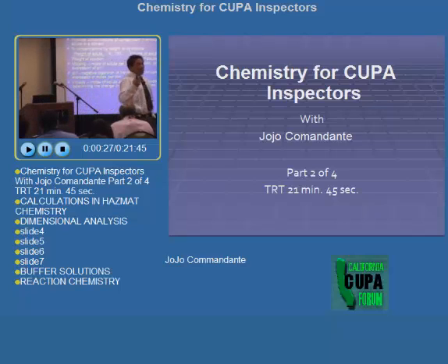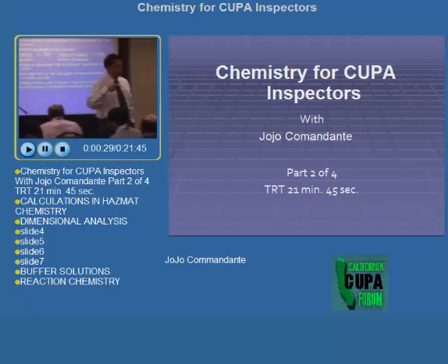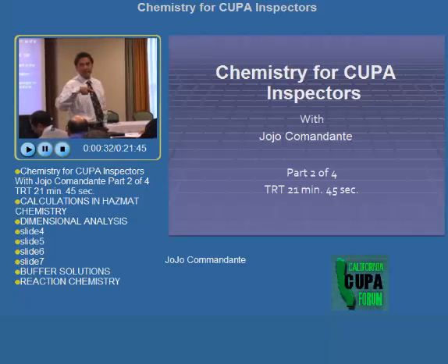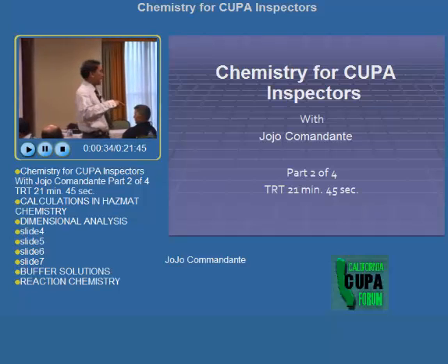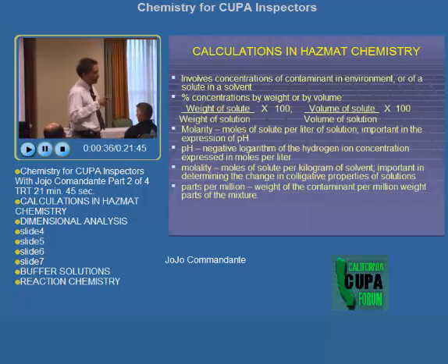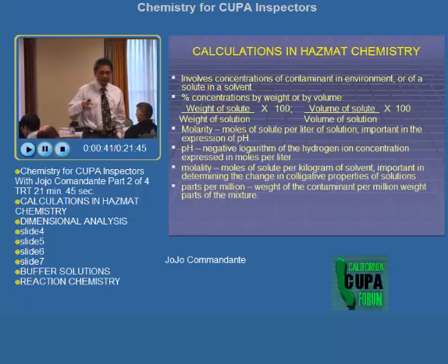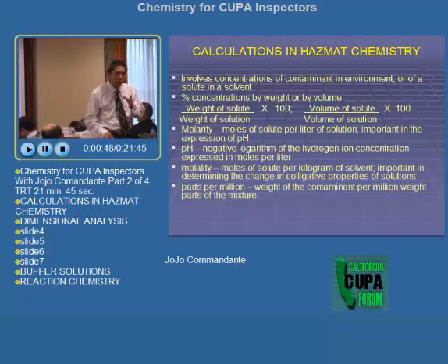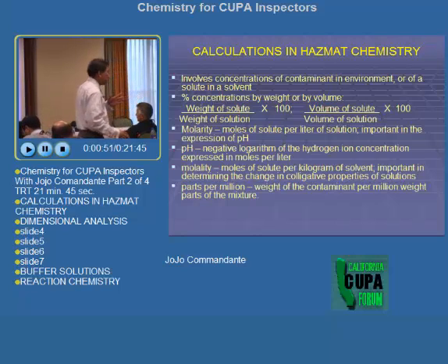Now, I encountered an incident wherein there was brine solution in the ammonia refrigeration facility, and, actually, it's an ice plant, I'm sorry, it's an ice plant. Why do they use brine solution? They use that to freeze the water in the boxes. Why? Because it has a way lower freezing point than actual water. So the water itself will freeze first, the brine will not. Okay? That's because of molality. Moles of solute per kilogram of solvent.